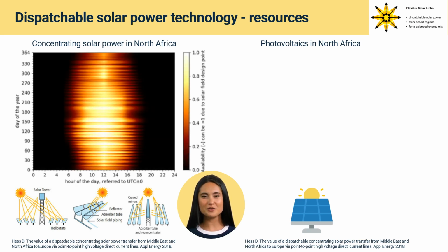We show the yield as a function of the collector power output availability. The presented plot is a so-called isopleth diagram which shows in our example the collector yield in North Africa hourly of each day for 1 year. In North Africa the yield of solar irradiation is almost constant during the year due to proximity to the equator. The presented plot also shows the nearly continuous day and night cycle over the year, which enables a short-term storage use case providing energy day and night almost constant during the year. The yield of the concentrating solar power collector has a high availability during noon and summer months.